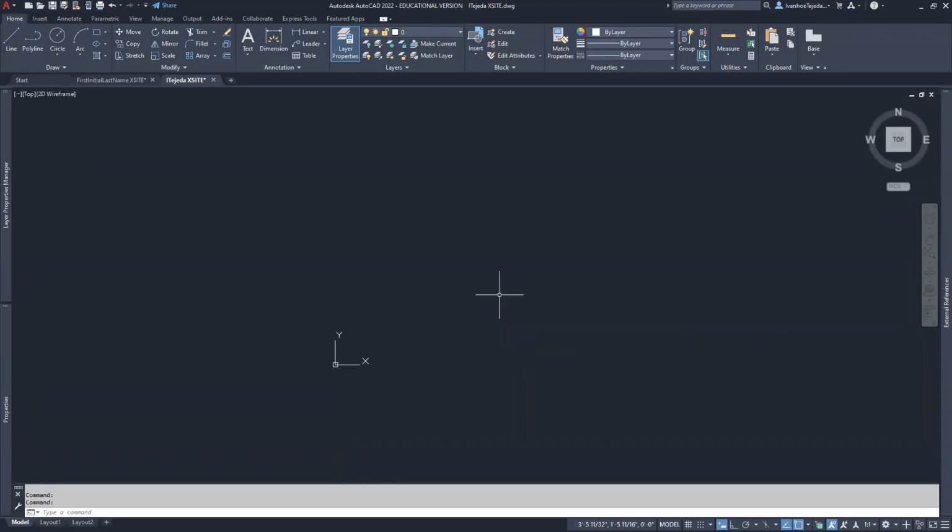I'm going to draw the lines that represent the property. So I'll make that my current layer. And now I'll start drawing my lines. I will simply type L and then use my enter key or my space bar, either one, allows me to start drawing that line. Specify the first point. It's going to be at 0, 0. That's my origin. And I enter.